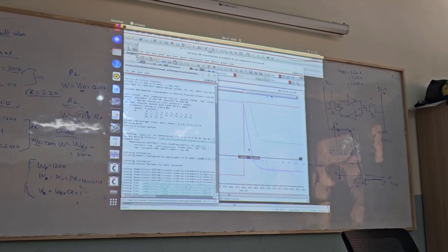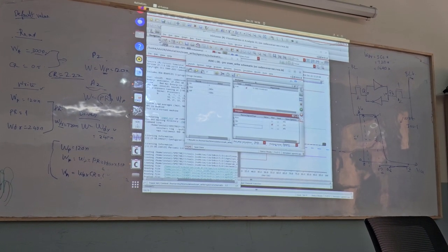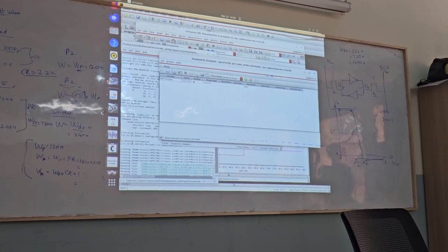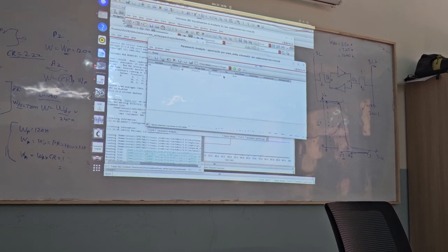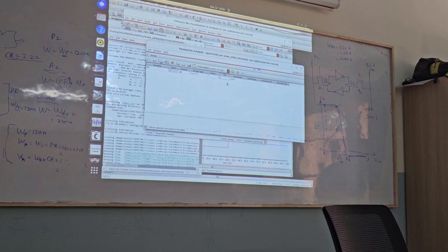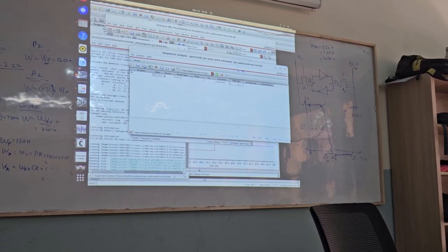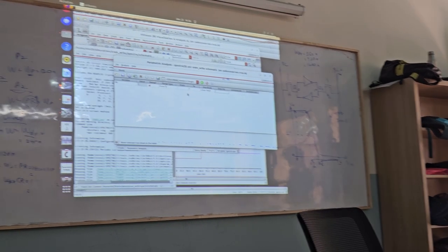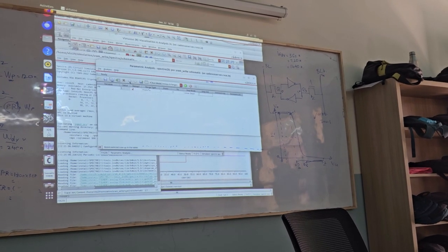Now in order to perform this, I'm not interested in the bit line bar as well as the enable signal. So I'll disable both of these, and I'll just go to tools, parametric analysis, and I just want to perform a sweep across PR. So this one varies from 1 to 3, and then I use the linear step. It was given as 0.5, I guess, in your manual. Please make it as 1 because the simulation will take a long time for us to complete the analysis. So of course, step size is fine.